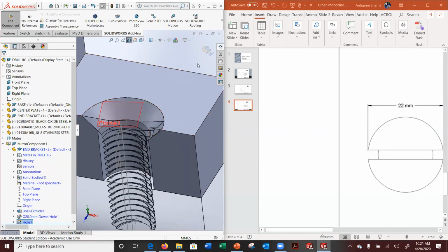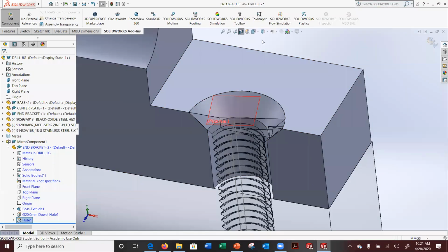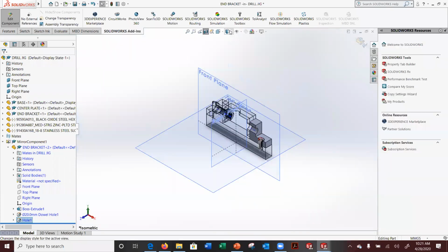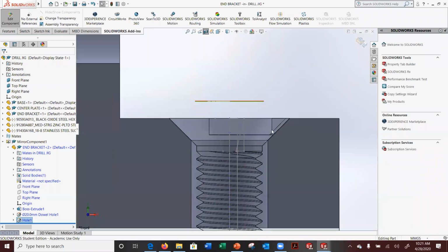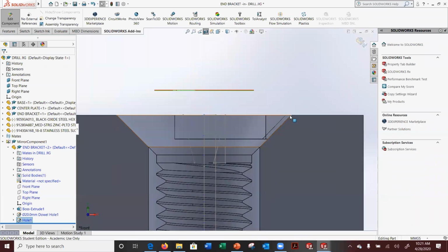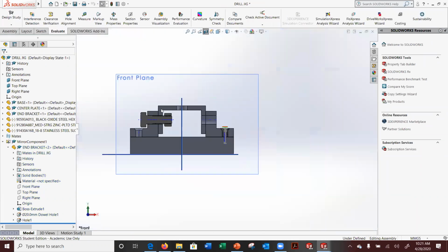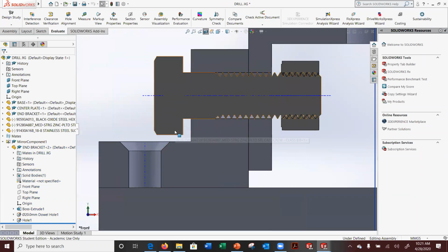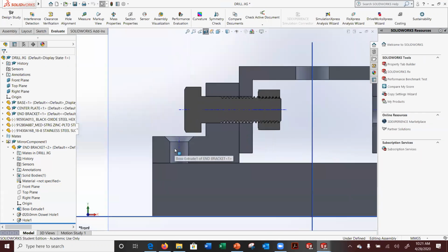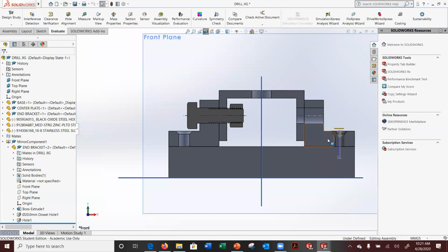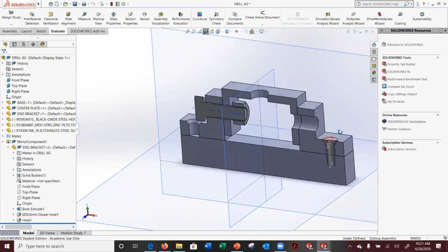it's a perfect match. In a perfect world, you can make fastener holes perfect. The world is not perfect, by the way, so typically we do make it just a little bigger because this has to be flush. You can drop in a little bit, but it has to be flush. The reason is look how much room I've given myself between my other bolt and this fastener. That fastener must be completely flush. Now I showed them on different sides, you'll notice, right?